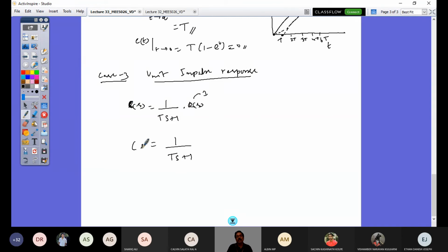So this is the best method of doing any experimentation. When you give a unit impulse as an input, whatever output response you get is the transfer function itself. Its equivalent in time domain is called the unit impulse response function, and that is useful for predicting the nature of your system straight away. It would also be more appropriate if the system is subjected to shock loads, right?